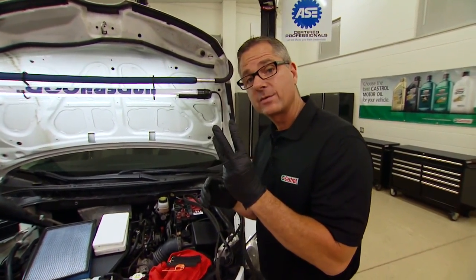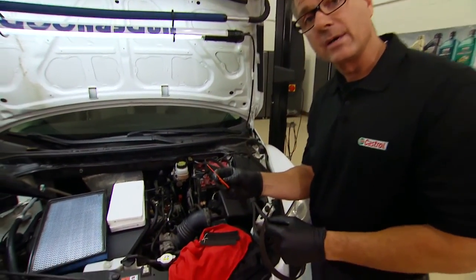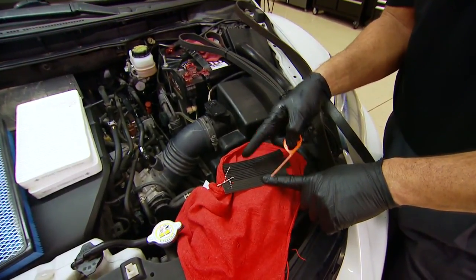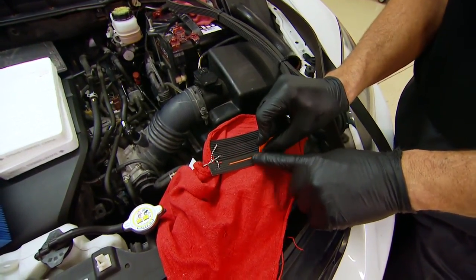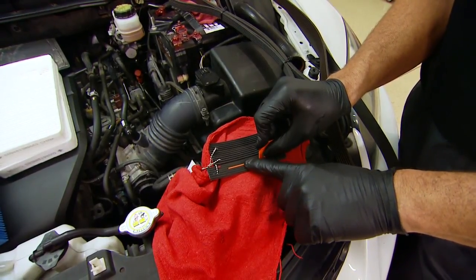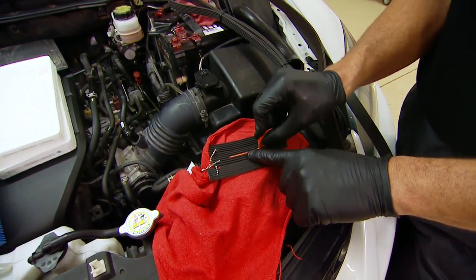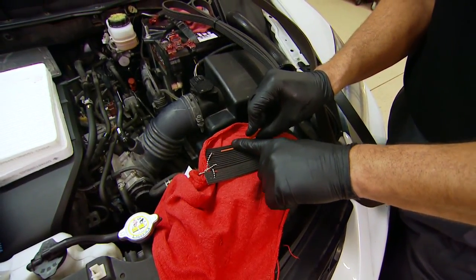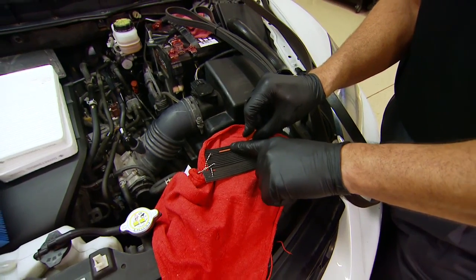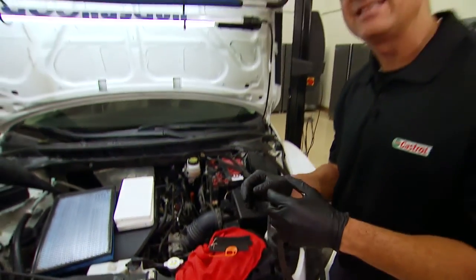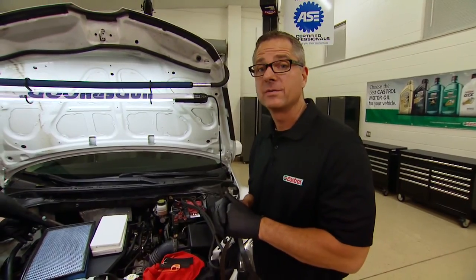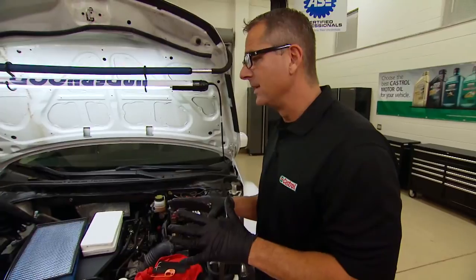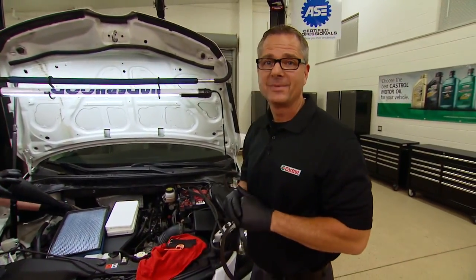And I have 3 belts here so I can show you. You actually need this little tool here, a belt checking gauge. And this is a new belt, an aged belt, and a worn belt. So if I put it right here, you can see it's protruding over the top. That's a new belt. That's not worn in those grooves right there. I come over here to this next one, it starts to sink down in there. And then the last belt, it's totally in there, in the grooves of the belt. So what's happening is this belt's actually transferring heat into the pulleys. It may slip. Your customer may have issues. So that's a good look at the belts, the hoses. Make sure you inspect the whole entire system so your customer's car will be in tip-top shape.